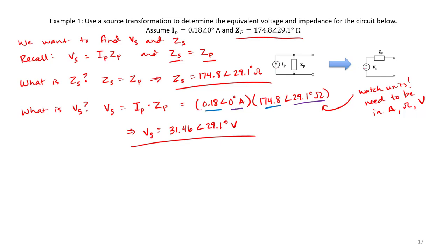And notice in this case, our polarity is pointing upwards for both. So there's no need to multiply this by -1. But if our Vs happened to be in the opposite orientation, then we would need to multiply by -1. So be sure to double check that you have indeed solved for the correct polarity and multiply by -1 if you need.